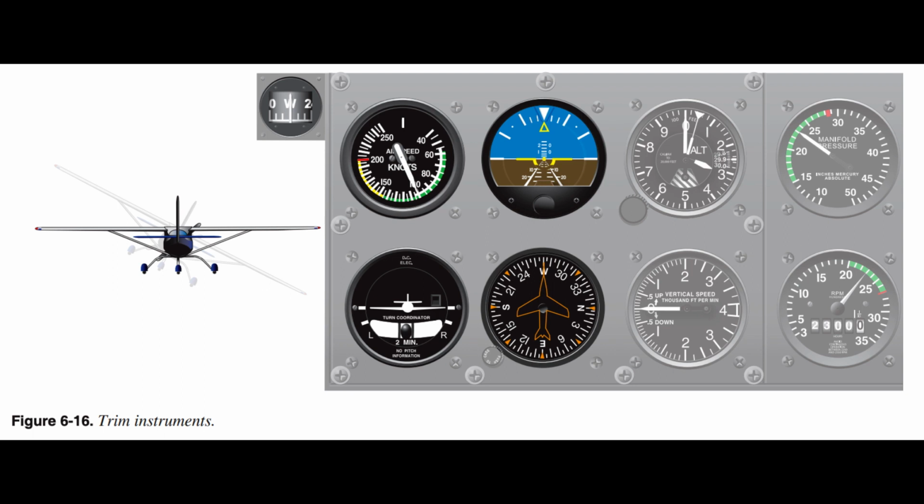3. Airspeed indicator supplies the most pertinent information concerning performance in level flight in terms of power output and is primary for power. Although the attitude indicator is the basic attitude reference, the concept of primary and supporting instruments does not devalue any particular flight instrument when available in establishing and maintaining pitch and bank attitudes. It is the only instrument that instantly and directly portrays the actual flight attitude. It should always be used, when available, in establishing and maintaining pitch and bank attitudes.